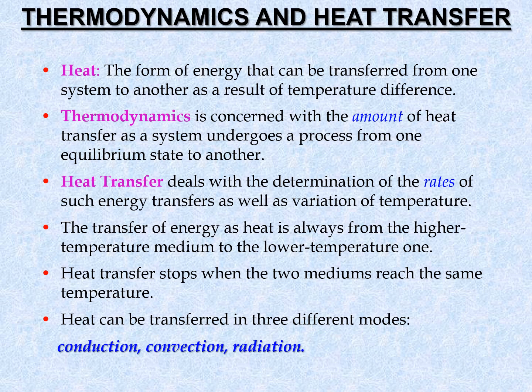Okay, the heat always goes from the higher temperature medium to the lower temperature medium, which follows the second law of thermodynamics. And heat transfer stops when the two systems reach the same temperature, which is the same as the equilibrium state. So whenever both systems have the same temperature, they will reach the equilibrium state, so there will be no heat transfer in this case. Okay, and last, heat can be transferred in three modes. Basically we have three modes of heat transfer: conduction between contact of solid bodies, convection between fluid and solid body, and radiation without any medium to transfer heat.